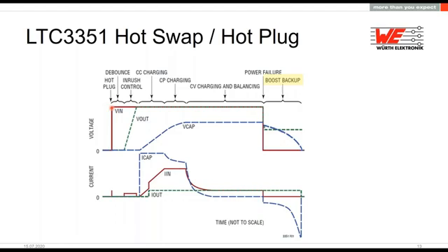There's a very small inrush current into the drain capacitance of the hot swap FET connected to the input. This is the small spike in the waveform, and depending on the rise rate of the input voltage, the duration and amplitude change.